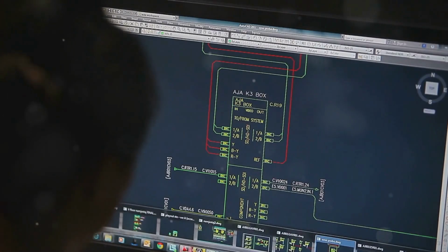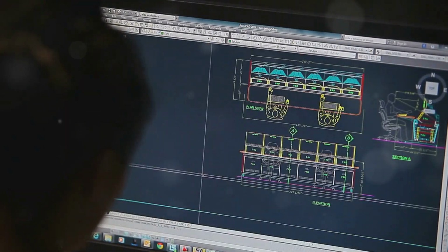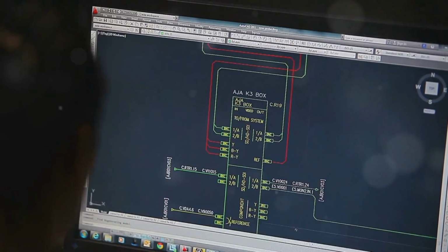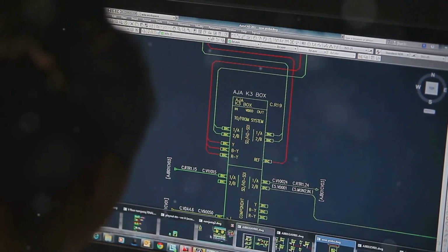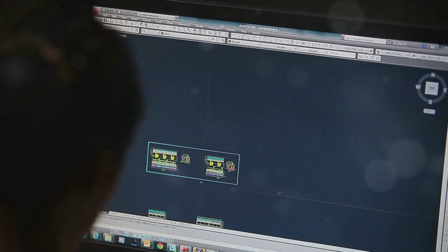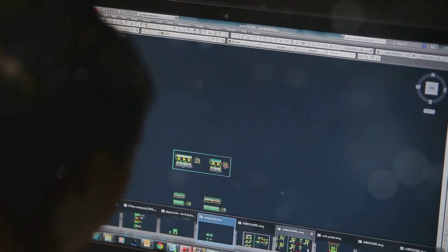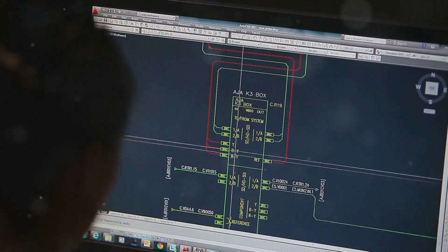Co-simulation. This workflow is ideal for two-way FSI problems where a strong interaction exists between the fluid and structure. It involves using separate solvers for the fluid, typically ANSYS Fluent, and structure, typically ANSYS Mechanical domains, and allowing them to exchange data at specified intervals.